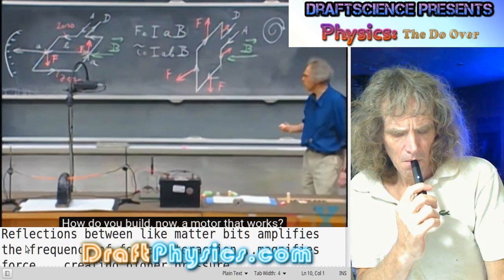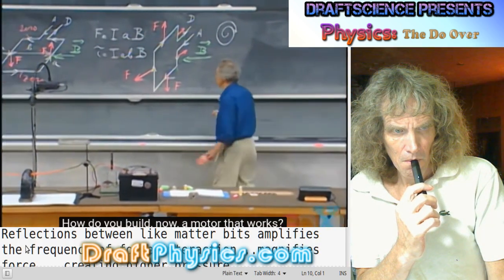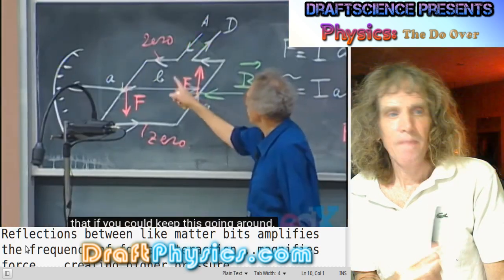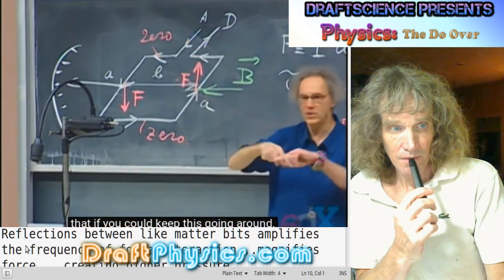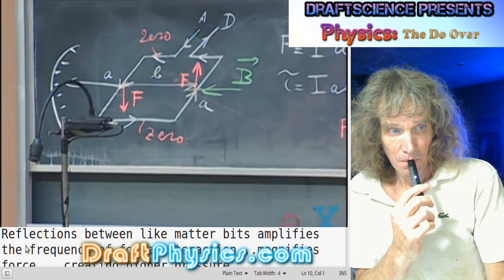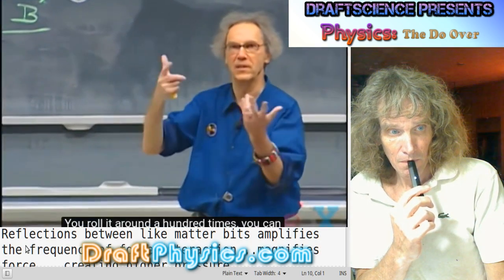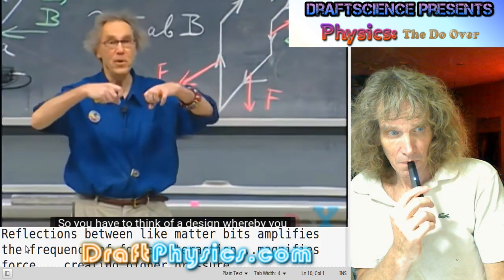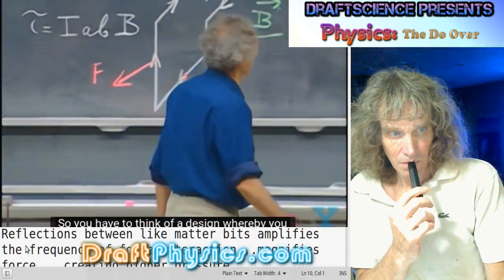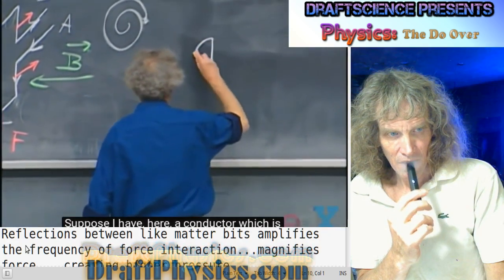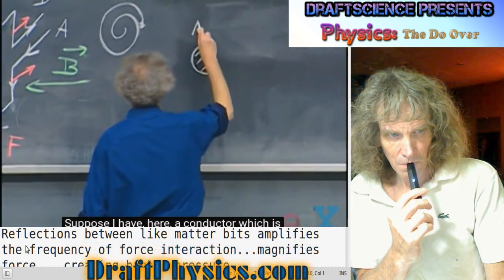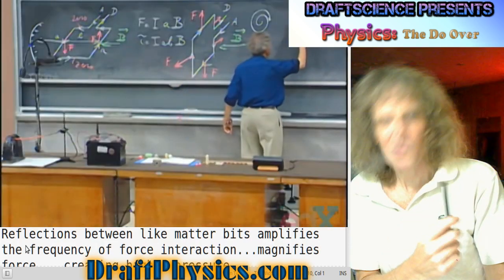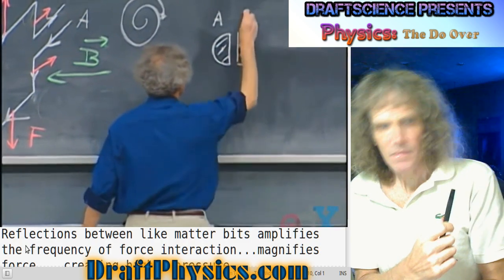How do you build now a motor that works? How do you get over this torque reversal? Well, it's not only the torque reversal that is a problem, but there is also the problem that if you could keep this going around, these two wires would intertwine and they would break. If you rotate it around 100 times, you can see what happens at A and D. It will break. So you have to think of a design whereby you have slipping contacts, we call them brushes. Suppose I have here a conductor which is connected with A, physically soldered to the wire at A. And here I have a conductor which...